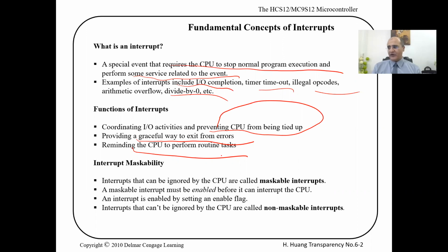A CPU running at 8 megahertz or 16 megahertz or 50 megahertz, you read the value of the temperature, or you do a task in, let's say, 1% of your time. What about the other 99%? Do you want to keep the CPU busy, consuming power and energy, doing nothing? You make it sleep. And when that 1 second expires, the hardware will wake it up and go read the new value. Okay, so these interrupts are very important.